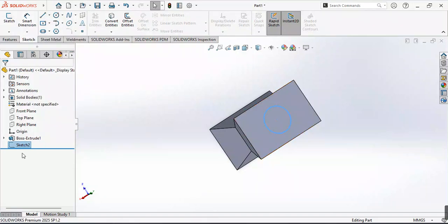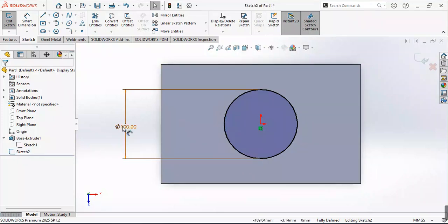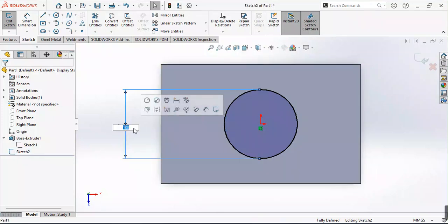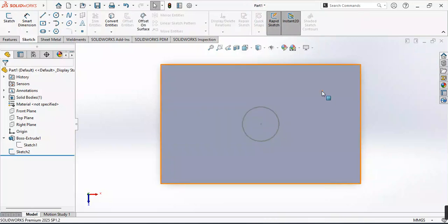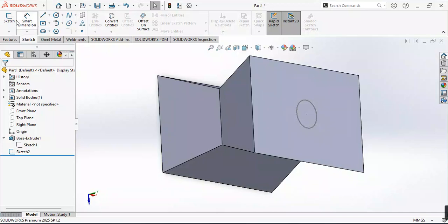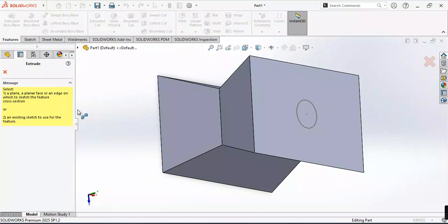You can just reduce the diameter of the circle. It's easy. You go to the sketch and edit. This is your diameter, so let's keep it 50. That is at the center, so you don't interfere with the contours. Now if you go to extrude cut,